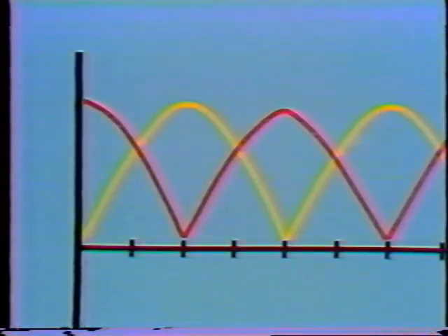Okay, so our modification works. Using 2 separate loops did decrease the ripple in the output voltage. It didn't have any effect on the peak output voltage. That stayed the same. But the average output is higher, as you can see on the graph.